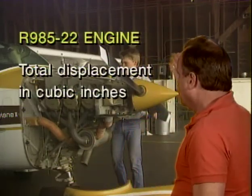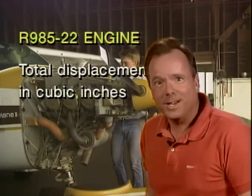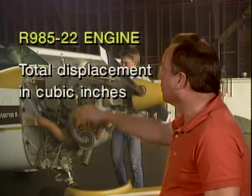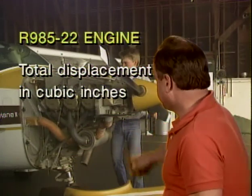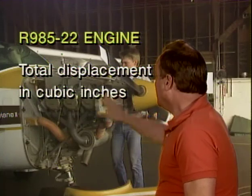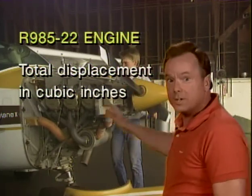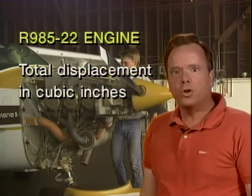All right, now on an R985-22 engine, what they're going to ask you on the test is what does the 985 stand for? Well, the R tells you it's a radial engine, and the 985 stands for cubic inches. That's the total displacement of the engine. The dash 22 we don't need to worry about, because it's some kind of manufacturer's designation of how that engine is configured for the particular airframe. So all they ask you on a test is what the 985 stands for. Well, that's the total displacement in cubic inches.